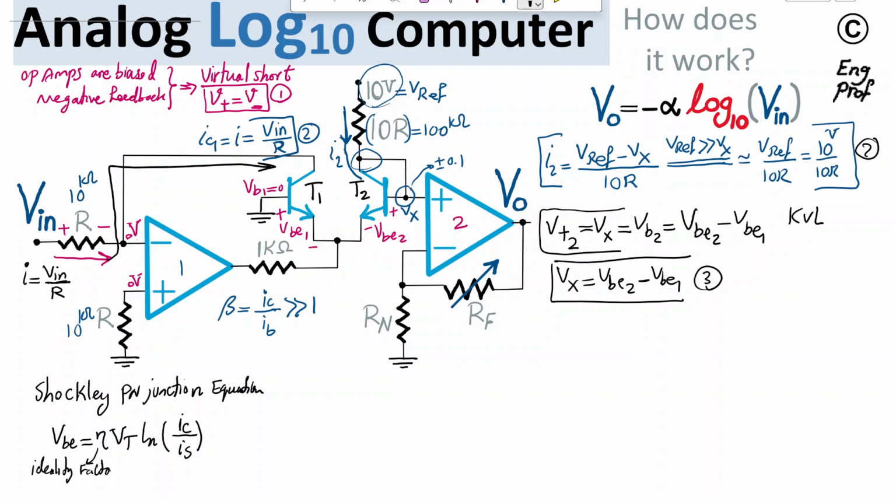In this equation, eta is the ideality factor. It's a value between 1 and 2. It's safe to say we can assume practically, in one example, that it is just equal to 1. There are many transistors with eta 1, there are transistors with eta 2. So for the ideality factor, I'm going to make the assumption eta is 1.